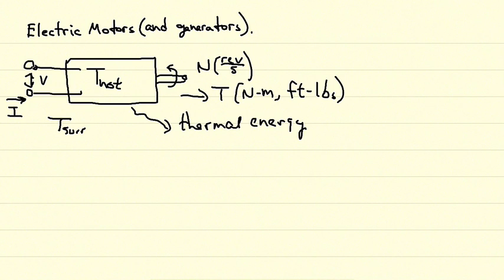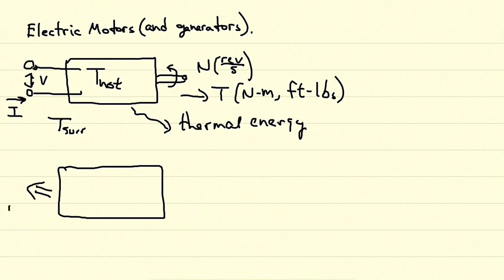So we can then start to take this information that we have here, and we can transfer this now into a thermodynamic control system. And so we can go ahead and draw that down here, where again we have our motor, and now we have some electric work coming into our system. So this is W dot electric. And again, I always draw everything in the positive orientation, which means that if the electrical work were exiting the motor, going from the motor into the surroundings, then this would be positive.